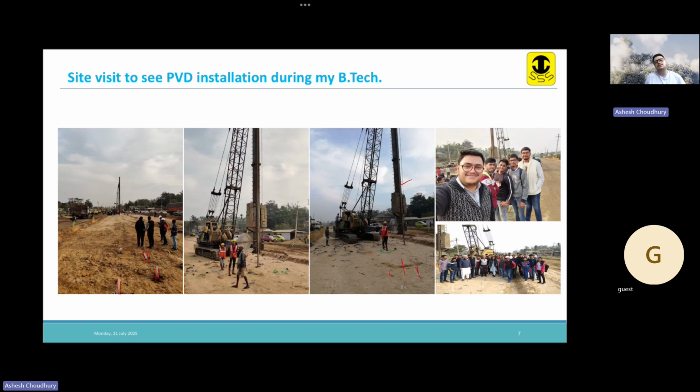So instead of sand drains, we can use PVDs. You should have studied sand drains in your basic soil mechanics courses when you studied radial consolidation. So these PVDs are an advanced geosynthetic that is used for radial, accelerated consolidation.